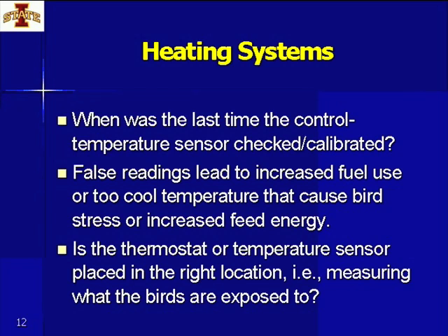The other thing we look at: even though the thermostat and temperature sensor are perfectly accurate, if they are not placed at the right location, especially for measuring what the animals are experiencing, that really doesn't do justice. So, for example, for broiler day-old chicks, if you measure, say, 4 feet above the floor, but the birds are at 2 to 3 inches from the floor, then you have to really consider whether the temperature measured is indicative of the bird's comfort level.